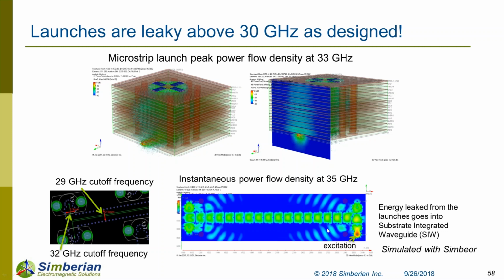Some structures on this particular board, like AC coupling capacitors, were less predictable. We found out that those were difficult to predict, and came up with a different approach for how to construct this AC coupling structure to make it more predictable.